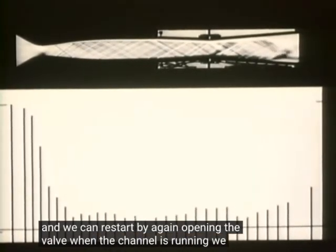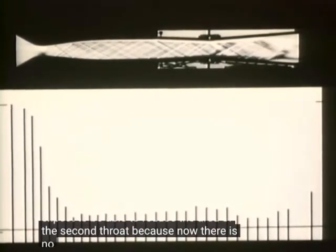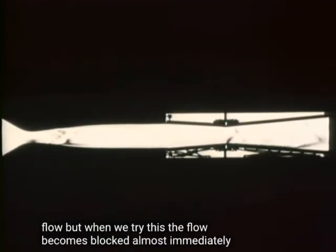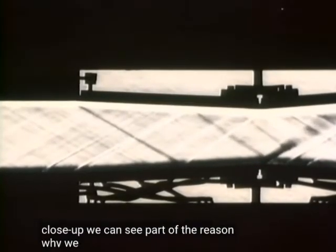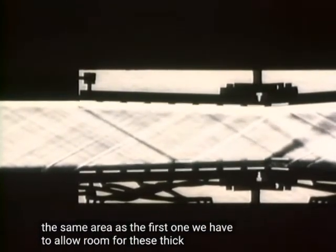When the channel is running, we expect to be able to reduce the area of the second throat, because now there is no strong shock wave in the nozzle to degrade the stagnation pressure of the flow. But when we try this, the flow becomes blocked almost immediately. We have to reopen the second throat in order to restart the channel. In this close-up, we can see part of the reason why we cannot close the second throat to the same area as the first one.